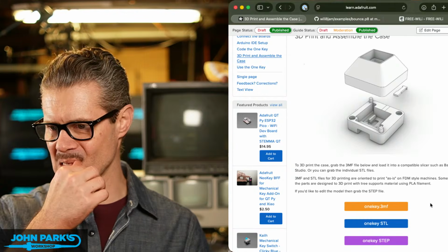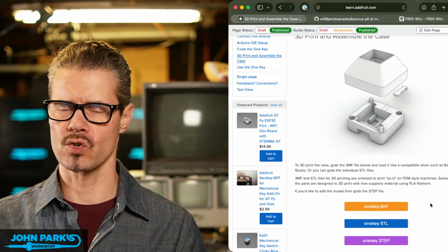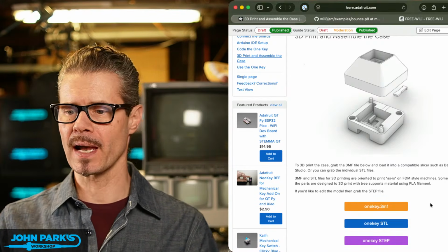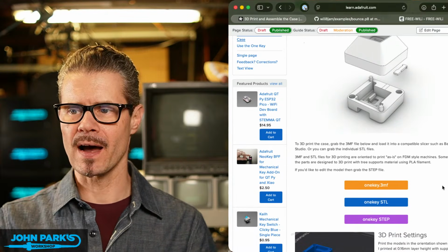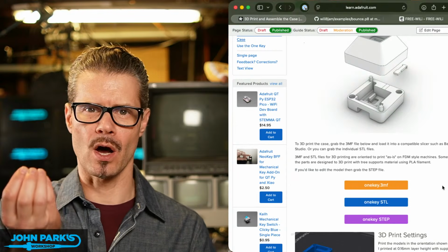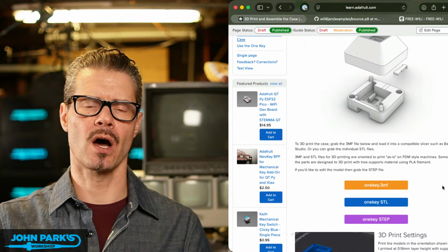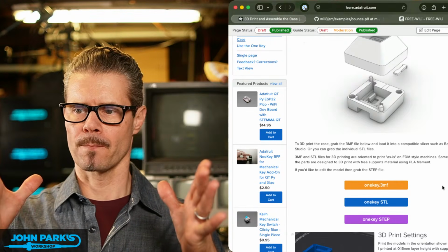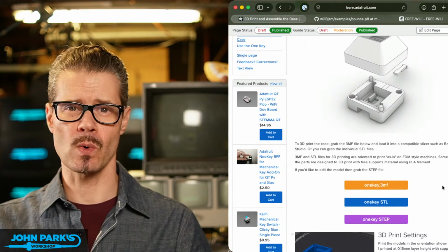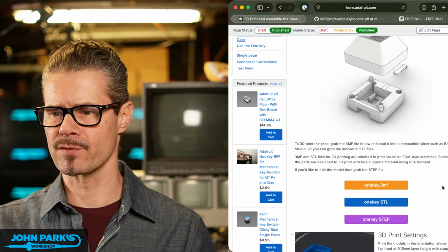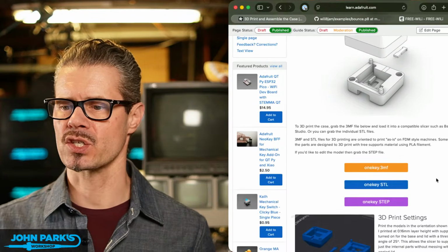And then we've started in the last, I don't know, couple of years, I think the Prusa folks started using slicers that have the 3MF file format, and so that's what this orange one here is. I'm using Bambu Studio, so in that file you get not just sort of the raw parts of the STL, but you get the model file as well as their placement and orientation on the 3D printer bed or beds if you're doing multi-print bed setups, as well as all of the print settings. So we don't have to include every little detail. It's actually in the Learn Guide, it's actually embedded in that file.